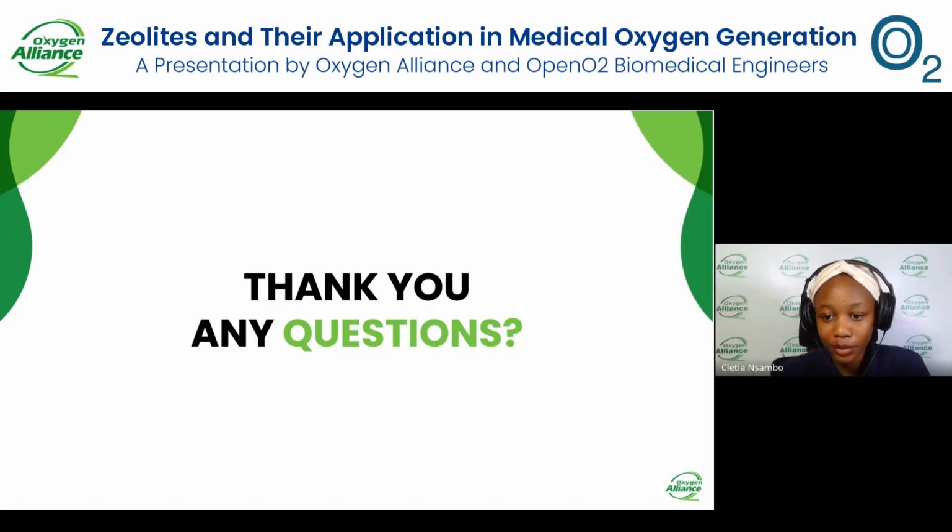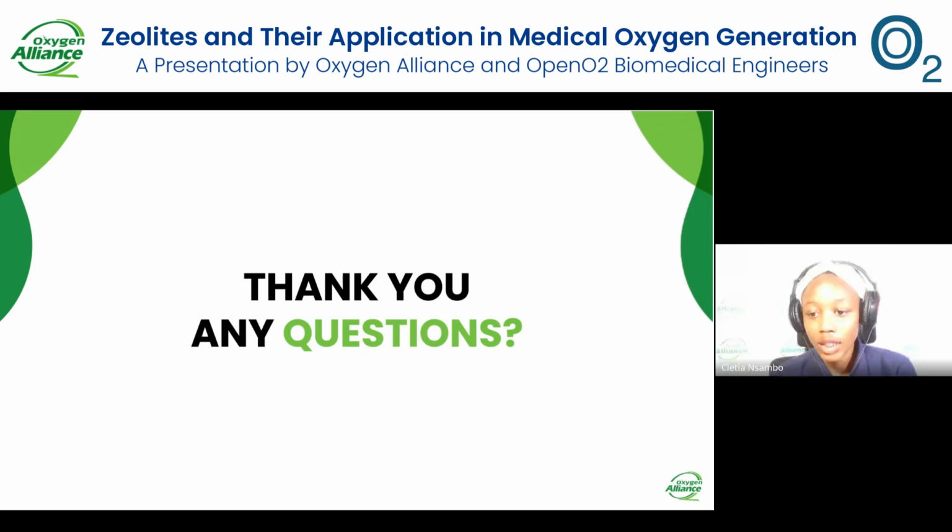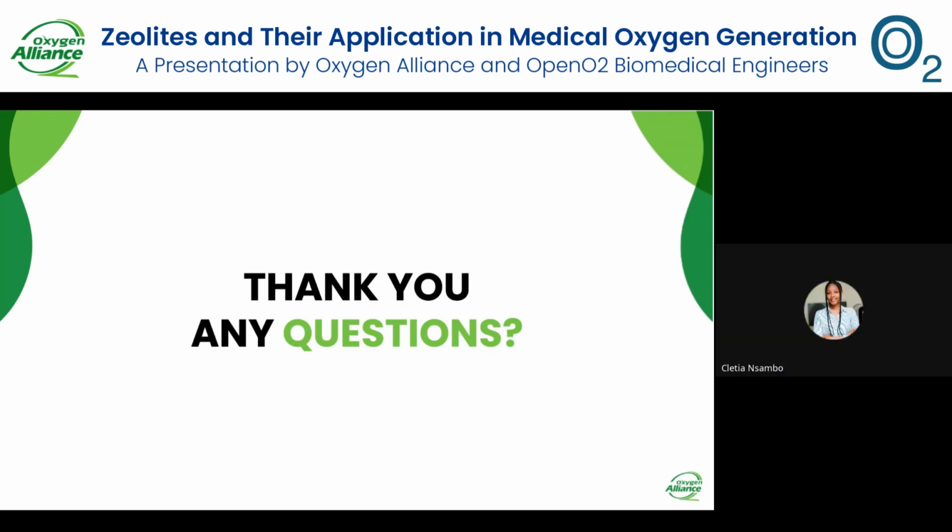The floor is still open for questions. There's another question from Olivia. They're asking what the working temperature of a PSA generator is. Actually, as Sharon was explaining on the question about temperatures, zeolite performs better at temperatures below 40 degrees Celsius. So anything below 40 degrees Celsius is considered. I hope that has answered your question.